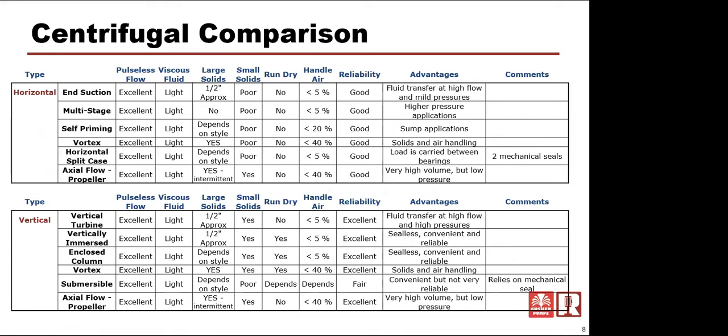Doing a centrifugal comparison between different types, there's the same type of chart here. Now we're going to get into centrifugals. Centrifugal, again, is something that induces flow rather than forces flow, if you will. And you'll see as we look down pulseless flow here, everything in a centrifugal pump is excellent. There is very little pulse to that flow. I mean, there may be small minute amounts, but generally it's very smooth flow.